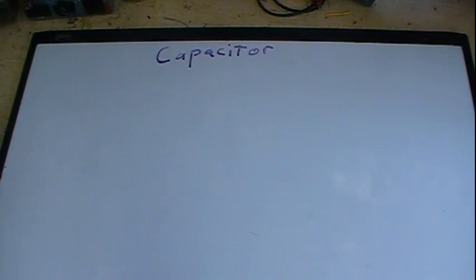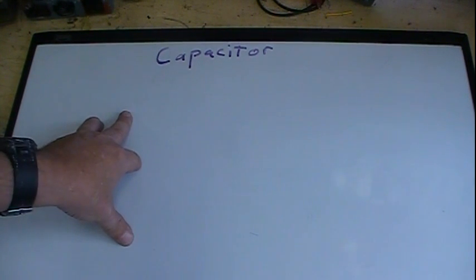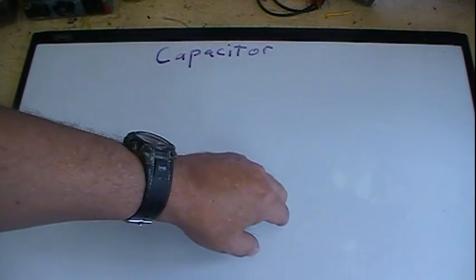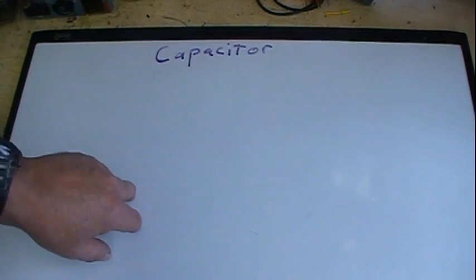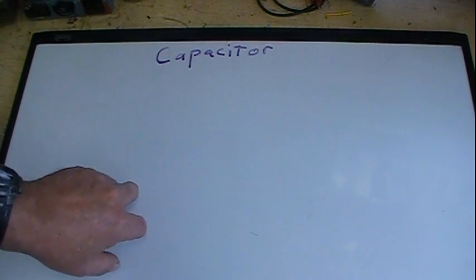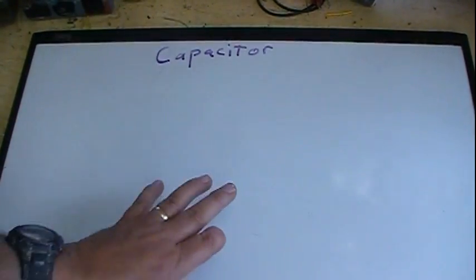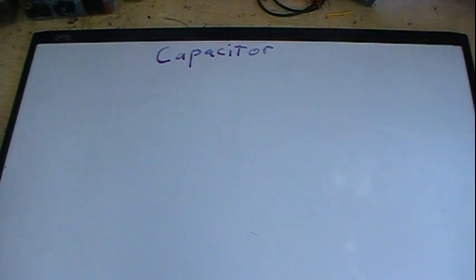Capacitors and AC circuits. Well, right off the bat, when a capacitor's in DC, for a moment you have a current flow for a fraction of a second, and then it stops. The cap gets fully charged. That charge on the cap equals the DC voltage you're applying. If it's a 9-volt battery, once the cap gets to 9 volts, end of discussion. No more current flow under practical, basic conditions.